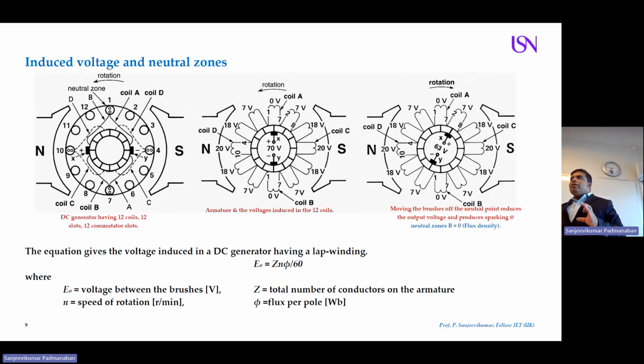And all these coils are copper coils. You know, in a copper coil, the inductor, you will have an internal resistance. I'm right? The internal resistance, what will it do? It will drop the current, I'm right? It resists the flow of current. So there will be a drop inside your inductor, in each conductor. So there will be a small drop in the voltage. That's why you are getting, you can have a look, 7 volt, 10 volt, 18 volt, depending on the positions. All these voltages will be added and you are getting around 70 volts.